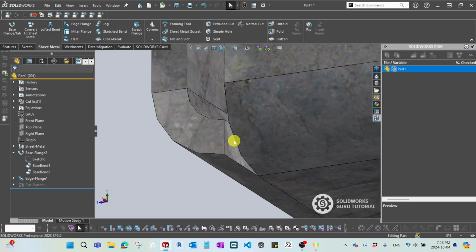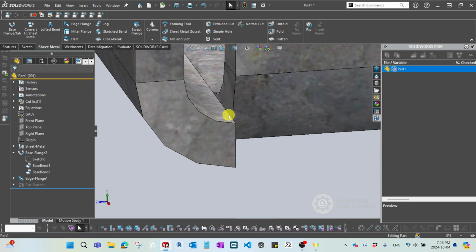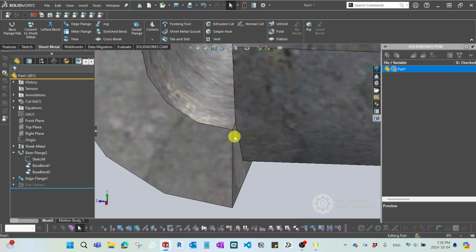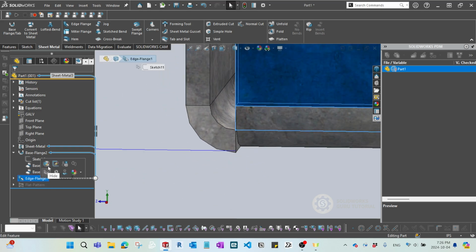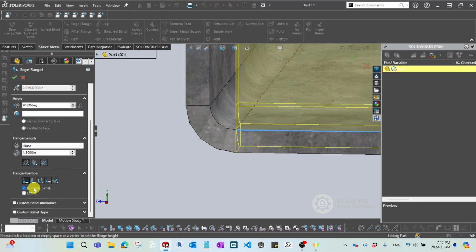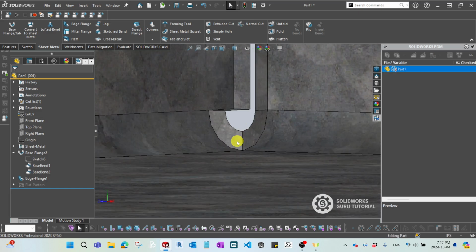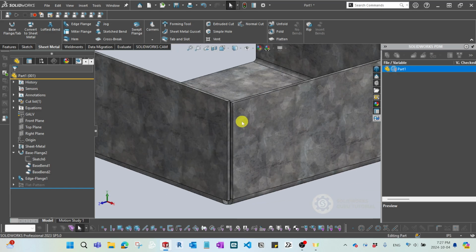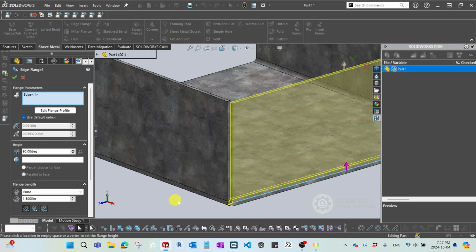And then that is what happens, and this bend looks very unrealistic, because it doesn't make sense to have almost zero thickness gaps like this. So that's why SolidWorks automatically assigns the trim side bends, so it makes more sense realistically when it comes to bends. That's one good feature when it comes to material inside.